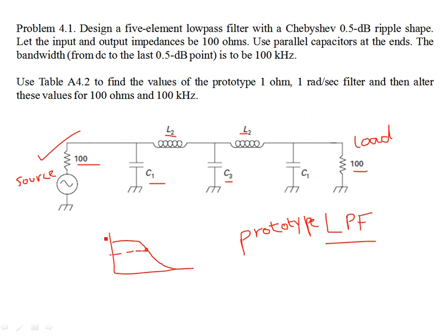So, for example, if it is V out versus frequency, that's the output frequency response. The 3 dB point is where the response falls to 3 decibels below 0 decibels, and we call this the cutoff frequency. This happens at the bandwidth of the filter, the pass band, and the stop band can start as specified at any frequency above the cutoff.